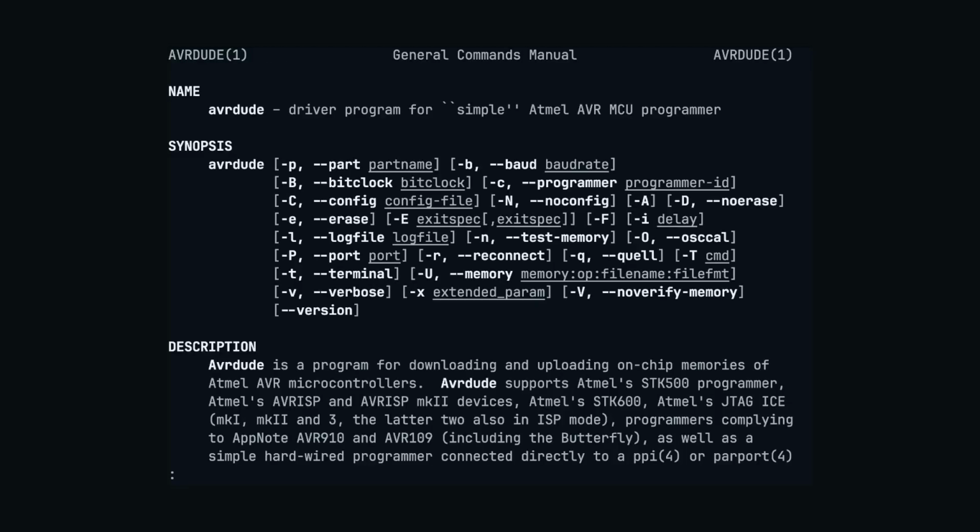From the man page, we can determine the exact command to run to achieve our goal. A lot of these items will not be relevant to us. We are just looking for the set of command options which let us read from the victim board. In our case, these options are as follows. -C. This option specifies the programmer we will be using to read the firmware. -b. This specifies the target board from which we will be reading. -P. This specifies the port on my desktop environment.